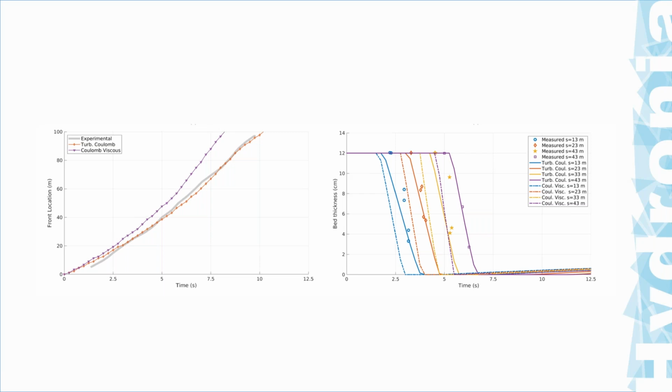And that also was our experience when we analyzed the Brumadinho Dam Break, which is a very big event with respect to this one, that you have to understand the differences between the rheological formulations, because the most common one was not the most appropriate one to replicate the real event.